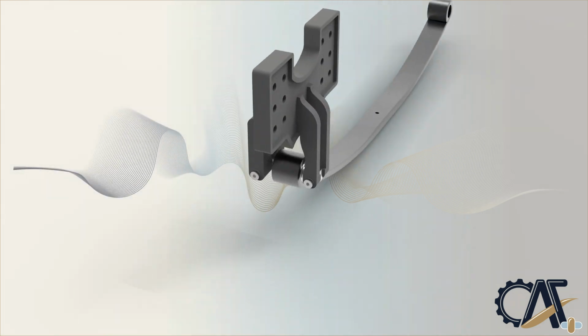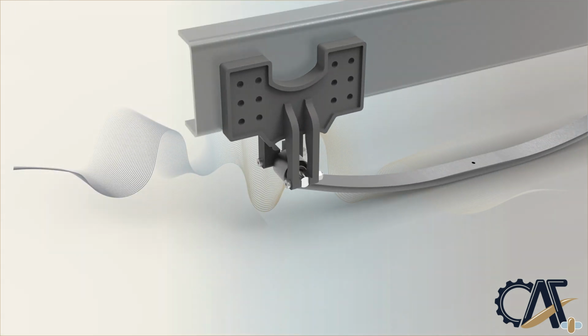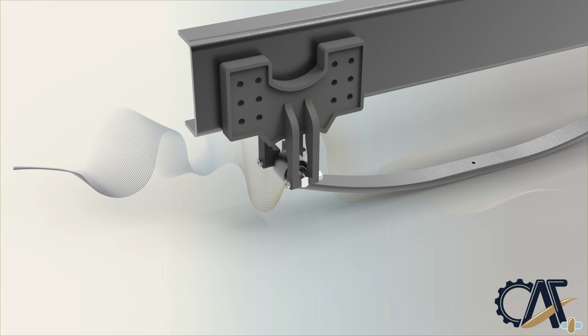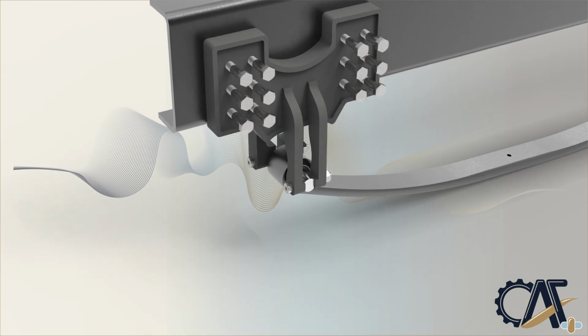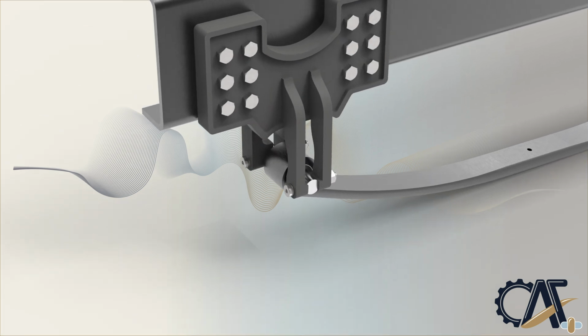The proper bushing size should be selected considering the maximum bending stress on the leaf spring and corresponding vehicle payloads that will have an impact on the leaf spring. All these calculations are performed during the engineering design process of the suspension system. The hanger is connected to the rail frame, which is a part of the chassis of the truck, with bolts. Now, we will demonstrate to you how the rubber bushing will enable the leaf spring to move relative to the chassis assembly in all the 6 degrees of freedom or deformation modes we covered earlier.